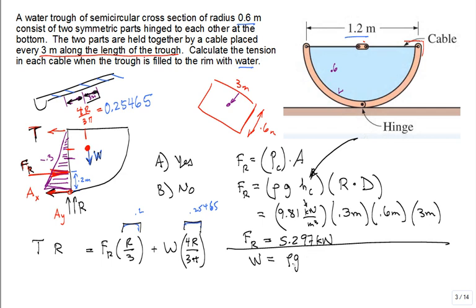I look at it and I say, I know the depth D, but I need that area. And then I push that area back a depth D. That gives me volume. The area of a quarter of a circle is 1/4 pi r squared, and I push it back a depth d. How many people like that for the volume of the water multiplied by rho g, you get the weight of the water? Good? Okay, we substitute numbers.